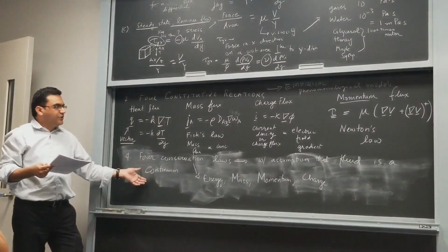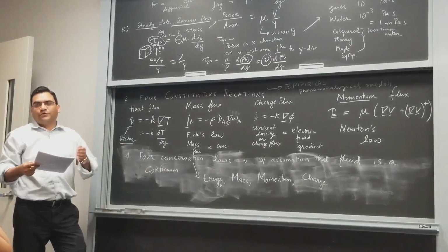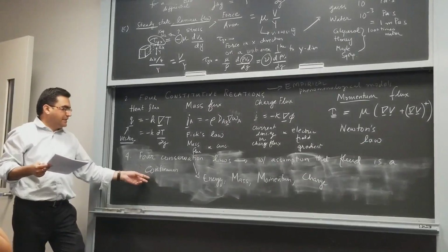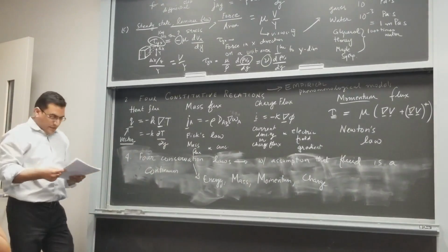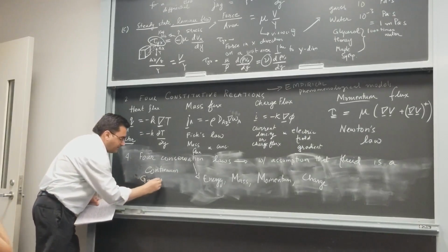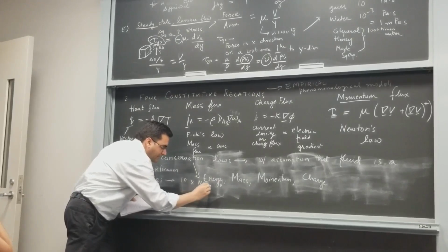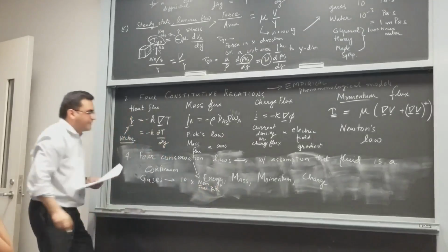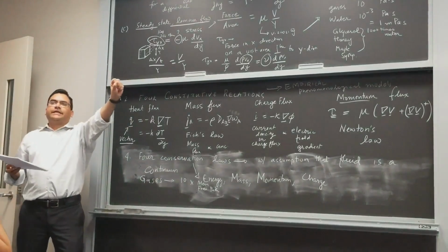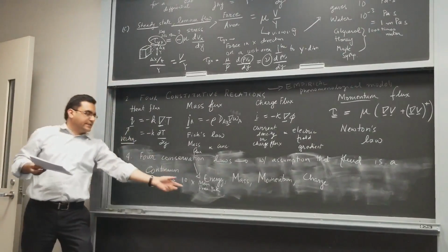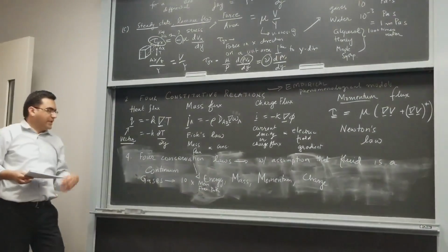Now, one thing we said here is we are going to assume that the fluid is a continuum. We all know all fluids, gases, and solids are made up of molecules. When you go from one molecule to another, there's going to be a certain distance, and so at a molecular scale they are not a continuum. So everything that we do applies only to a certain length scale. For gases, that continuum is 10 times the mean free path. Mean free path is an idea that comes from the kinetic theory of gases, but all it tells you is that gas molecules are always dancing around, and they can fly to great distances before they encounter another molecule, and those great distances are the mean free path. That mean free path is usually much larger than the size of the molecule, so this distance has to be relatively large.